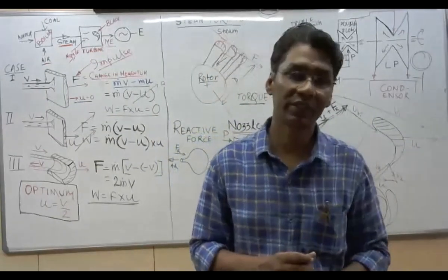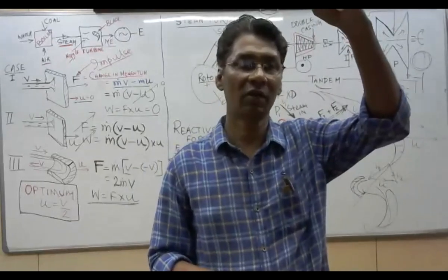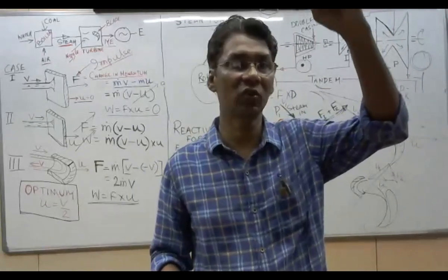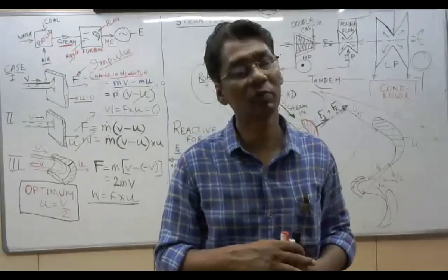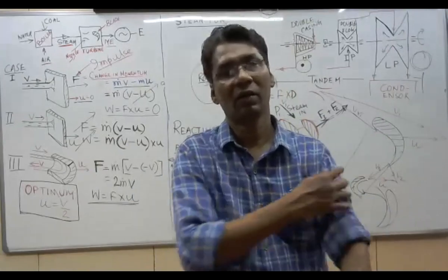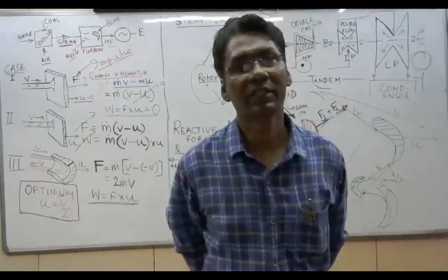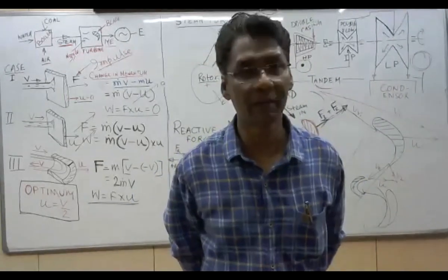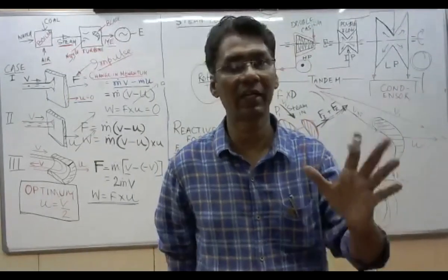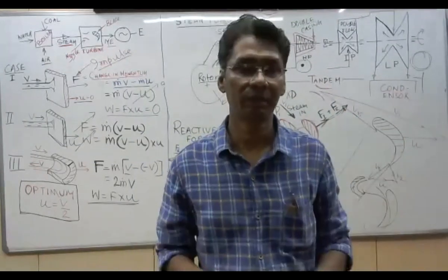Also, the second law of thermodynamics shows that there are two sets, one is the source, one is the sink. In the power plant, the sink is the condenser, the source is the boiler. So there should be exchange of heat between the two reservoirs. It is not possible to generate power without exchanging heat between two reservoirs. That is the fundamental of the second law of thermodynamics. You cannot violate that. You cannot remove the condenser. You have to condense the steam to recycle it, and also to get power output.